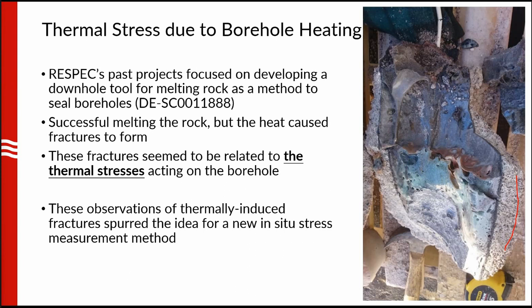But what they found out is that the heat caused the rocks to fracture. So the purpose was to seal the borehole, but because of the fractures caused by the heating, it kind of defies the purpose. So in a sense, they couldn't reach the final objective. But one thing that was clear is that these fractures seem to be happening because of the thermal stress that is caused by heating the borehole. So given that they had this background, that's how they came up with the idea of intentionally creating breakouts by heating.